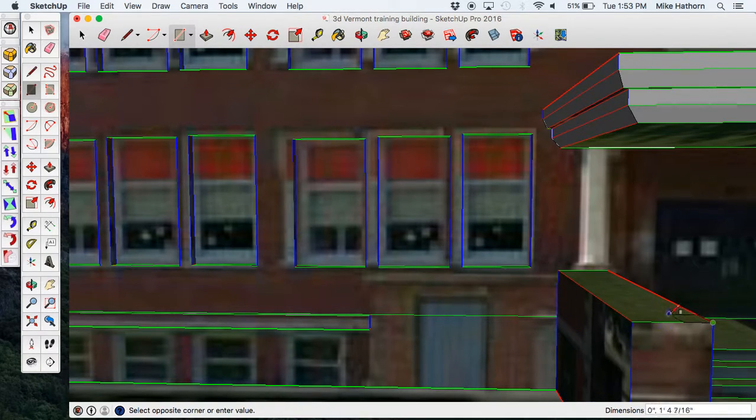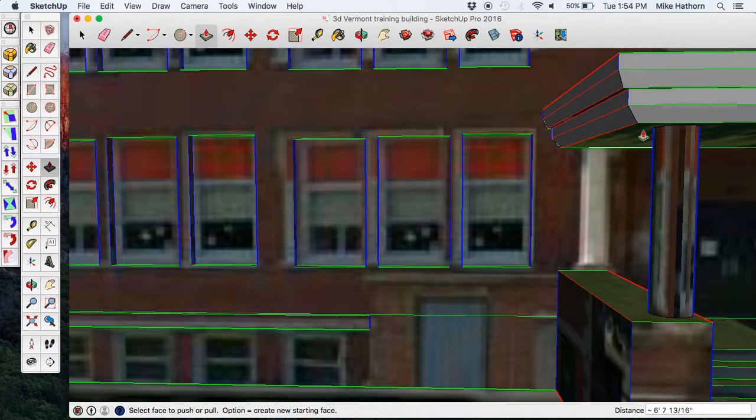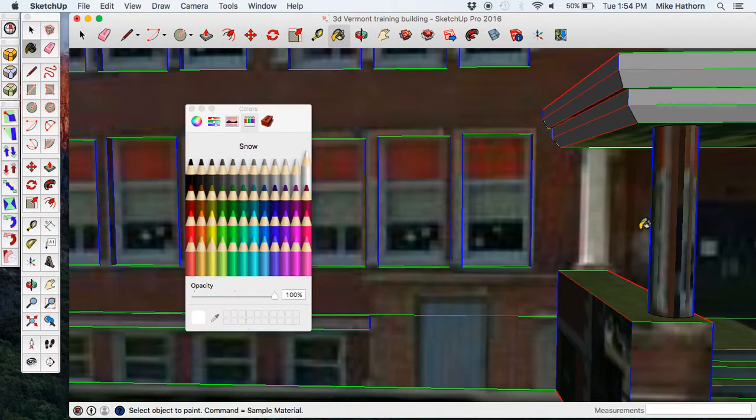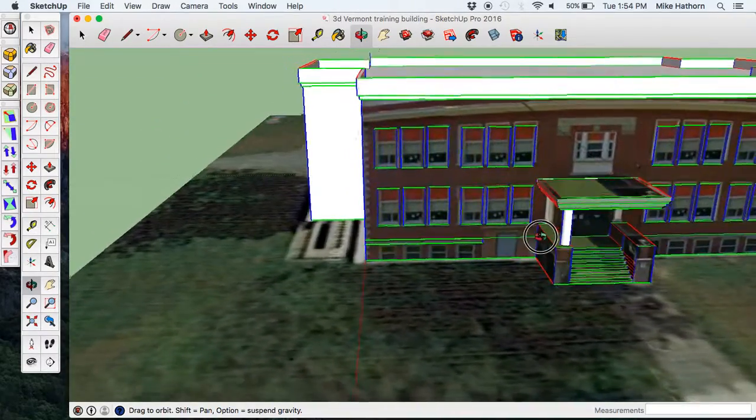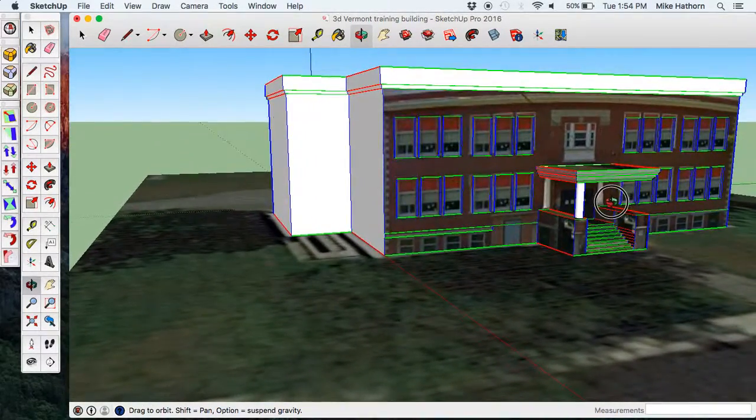and then you can start working on the details. I usually start with a rectangle and it will tell you when it's a square, and I'll just do one of these quickly. Golden section tells you it's a square, and then I'll draw a line from corner to corner because I want this middle point. So when I use the circle tool, and I usually just click C on the keyboard, it's a shortcut, click once on the midpoint, draw it to the size you want, and then erase all of the excess, and then you can pull that right up to the top. And then if you want it to look more like what it looks like, you can paint it.